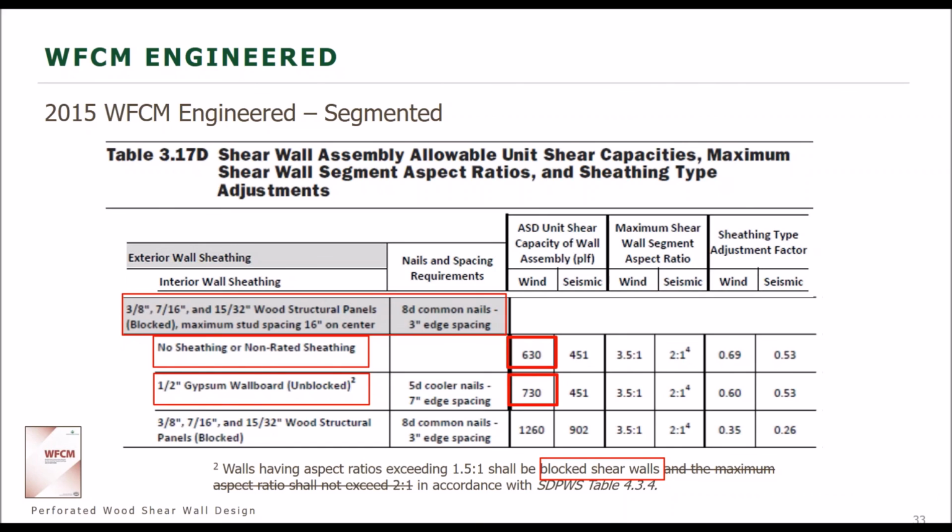Great. Another question came in regarding using CAD drawings and locating shear wall openings, and how does that interact with the WoodWorks software? Yeah, it's a good question. Essentially, the CAD drawing is a tracing paper. The software is not going to recognize where walls or openings are on the CAD drawing.